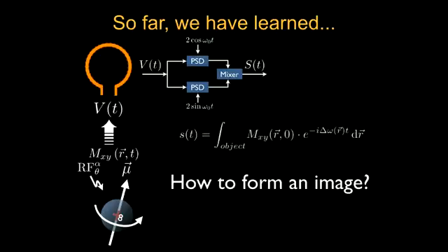And then the next question is how do we form an image based on these signals? The way it works is that we can control this omega function by using different gradients, particularly the Gx, Gy, Gz gradients. By having this ability to manipulate the frequency over different locations, we can form an image.